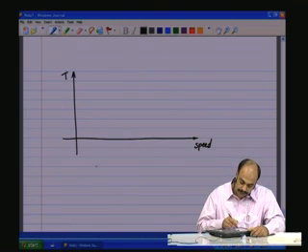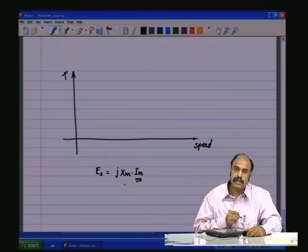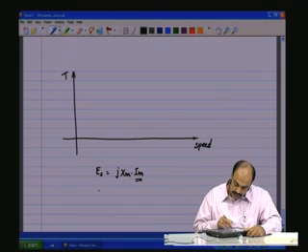But if, let us say, the applied voltage E stator is such that, let us say, the voltage across the magnetizing reactance is now Es, which is j Xm into Im, the magnetizing current. Let us say we want to keep the magnetizing current constant, which means we need to keep Es by Xm constant.